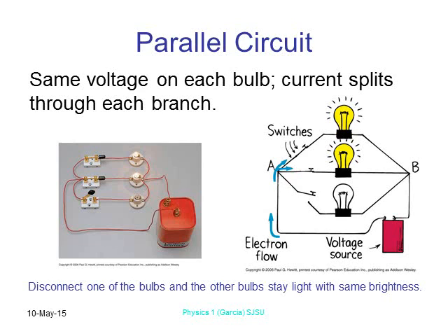The downside of this, though, is you're using 3 times the electricity from your battery. So there's always a payoff. There's no free lunch here. This isn't magic. In the first one, the series one, if we're using 1 times the electricity, in this one we're going to be using 3 times that because we have 3 bulbs in parallel.